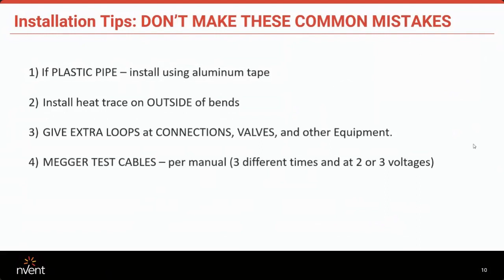Say if it's on a pipe, maybe you've installed it on the pipe, but it's before the insulation is put on. And then the 3rd time is the complete final one. After the insulation and components are installed, you do that 3rd testing. And you do have a spot in the book that you can write all of these results down.